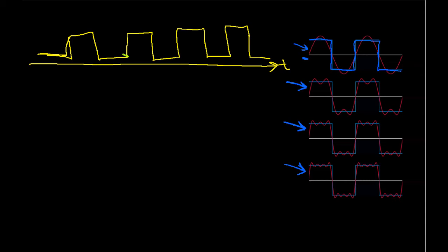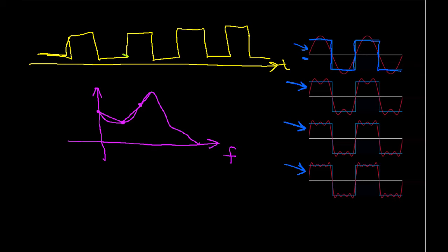Speech recognition and speech compression use the idea that I can break signals into different frequencies. For example, in speech compression, you might take a signal and convert it into a frequency domain representation which might look something like this. The horizontal axis is frequency, and the vertical axis shows the power at each frequency in the signal. You might compress this signal by representing its frequency spectrum by a bunch of straight line segments. You can transmit the parameters of the line segments over a communication channel using far fewer bits than you can transmit the whole frequency spectrum or the original time signal.